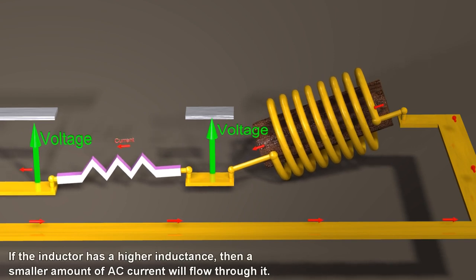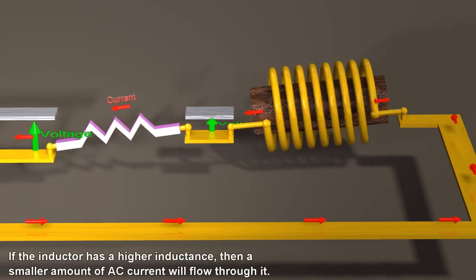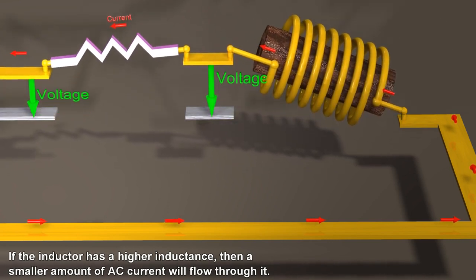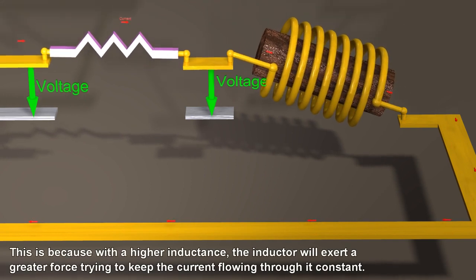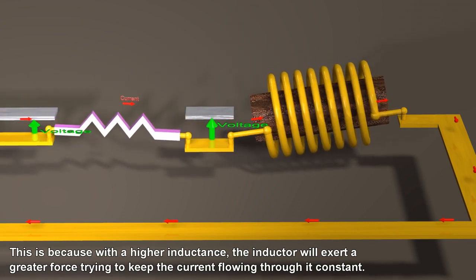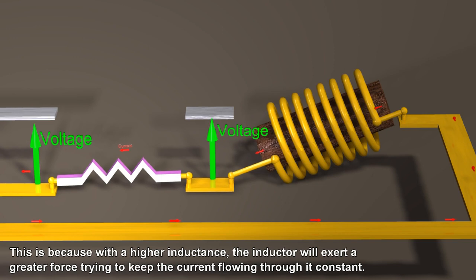If the inductor has a higher inductance, then a smaller amount of AC current will flow through it. This is because with a higher inductance, the inductor will exert a greater force trying to keep the current flowing through it constant.